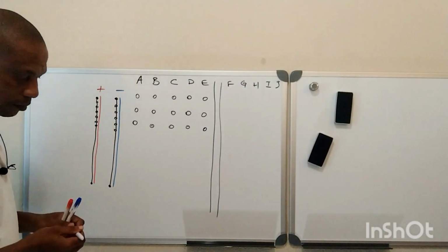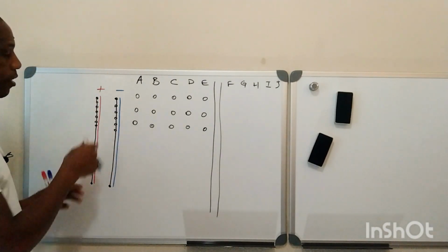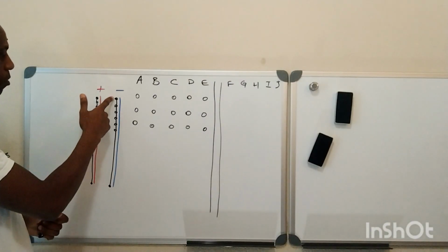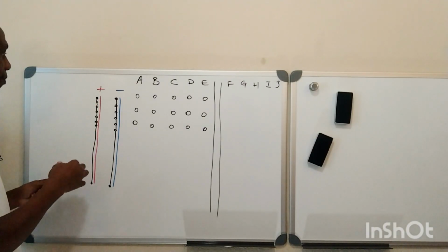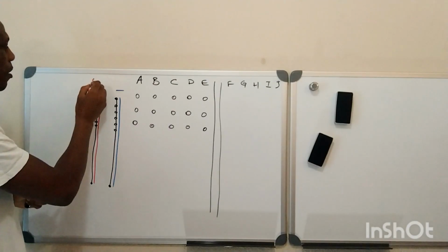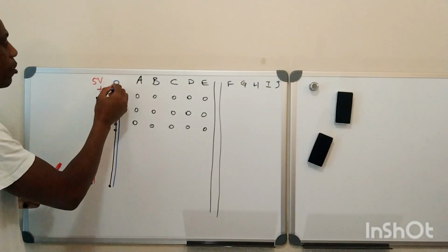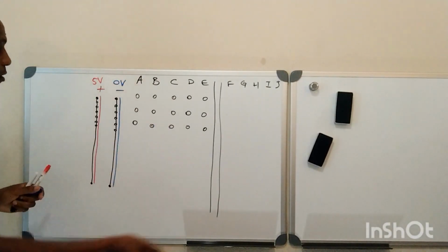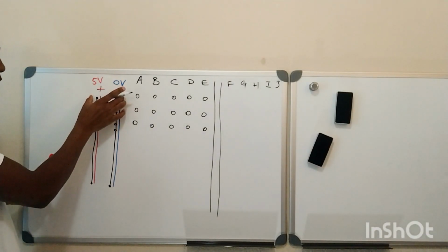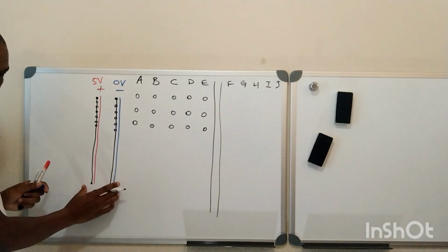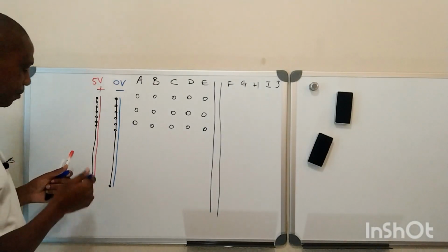Underneath that white thing, where they wrote all these things, there's a conductor that is running from top to bottom. So if you connect 5 volt this side, and you connect the negative side of the battery this side, if you measure here, you'll get 5 volt at the top. The same will happen if you measure at the bottom, because the current will be running down. Does it make sense?